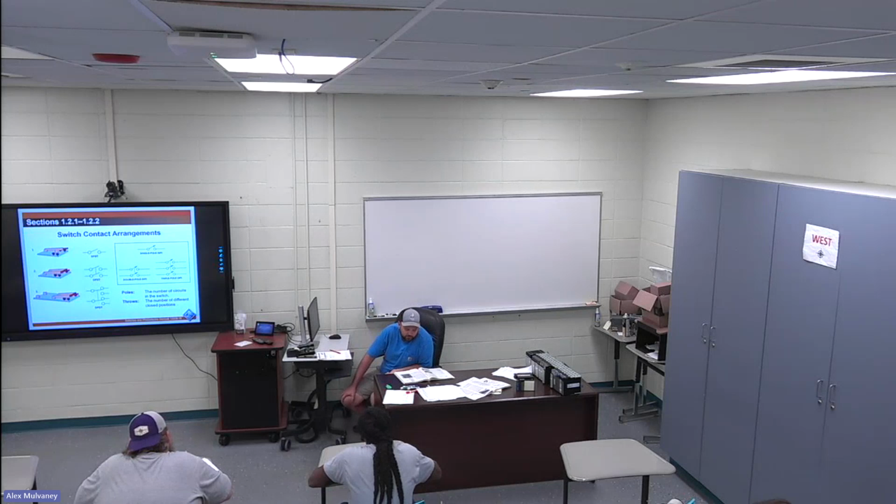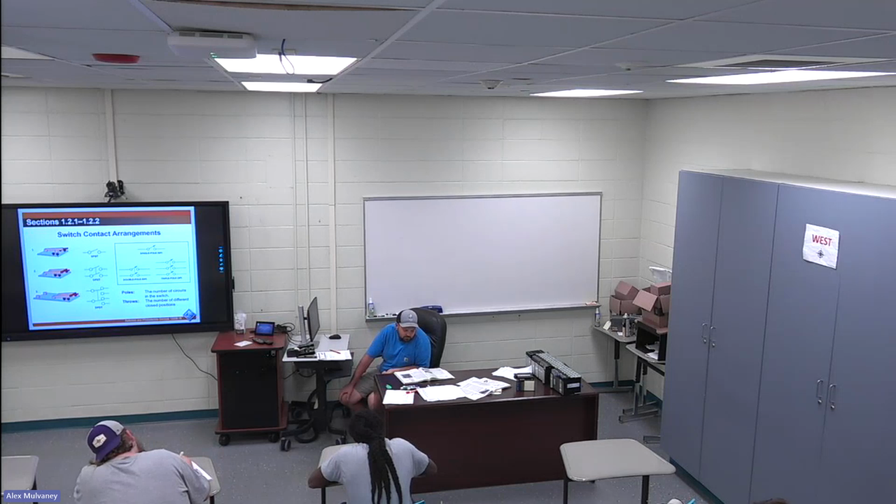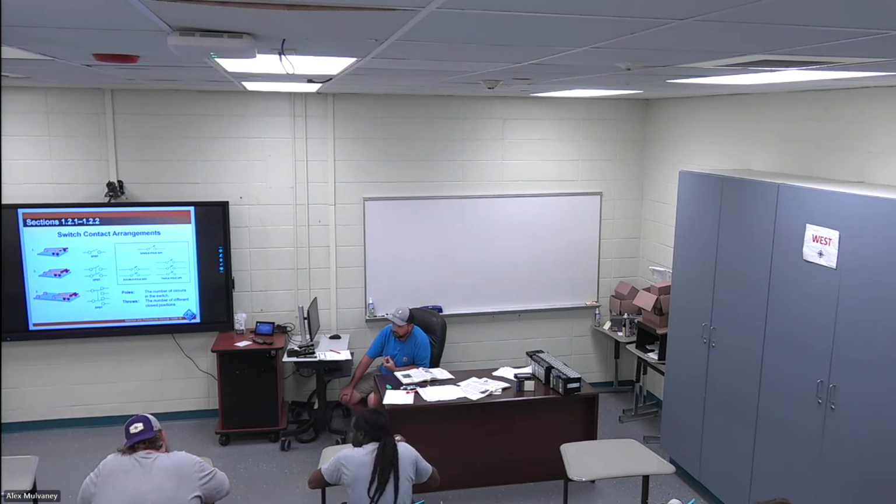1, 2, 2, pole and throws of a switch. First sentence is highlighted. The pole of a switch is the place where the movable contacts are attached. Second paragraph, first sentence is also highlighted. A single pole switch will make and break only one conductor leg of a circuit, whereas a two pole switch will make and break two legs of a circuit, and so on. Third paragraph, third sentence: the poles and throws of a switch are often abbreviated as shown in figure 4.